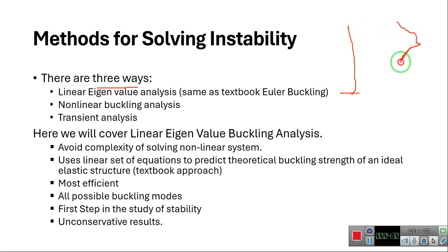This can be the S shape. This is the second mode for the same beam. So these are the modes. We can determine the different failure modes, and it doesn't involve further complex analysis. That's why this is very easy and not computationally very expensive. It doesn't give us a very accurate result, but it's a very first step to perform stability analysis on the body.